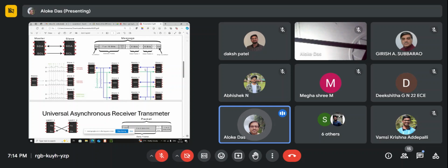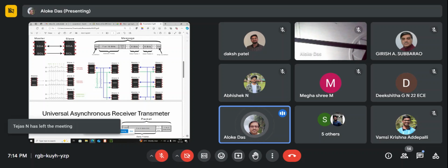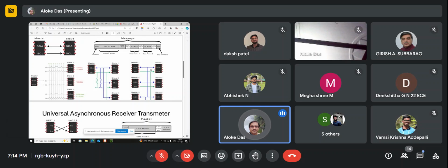Then the control signal from that unit should go to the control signal of those bufif gates. If you see the truth table of the bufif gate, if the control is 0, the output is high Z, meaning high impedance. And if the control input is 1, then the value propagates from input to output.